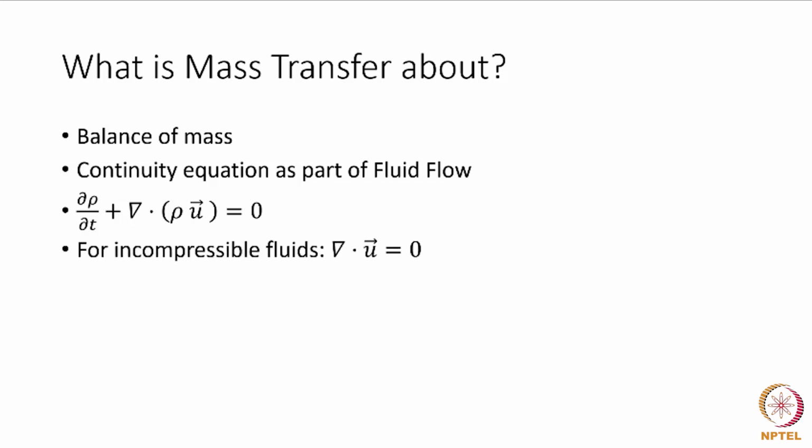The simplified form of the equation for the continuity is given here, which again is for a situation where we have an incompressible fluid. We will see how we bring about the mass transfer and conclude that the continuity equation will still hold. The only thing is that we need to give a definition to what u means and what ρ means.